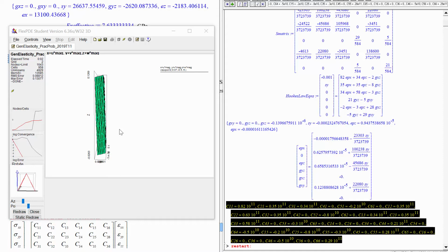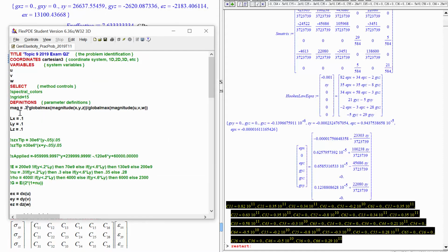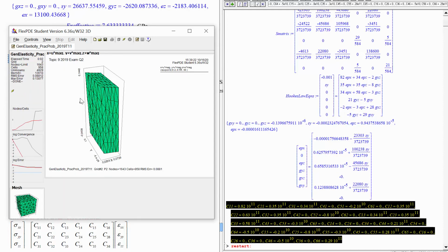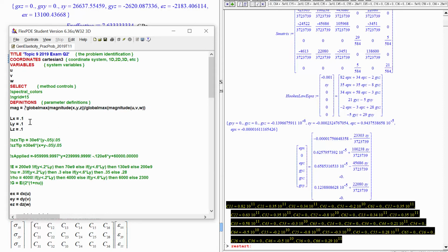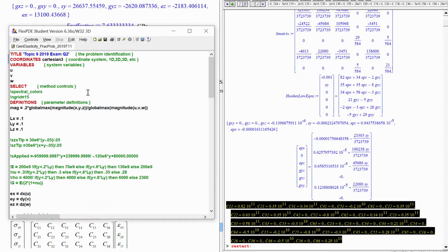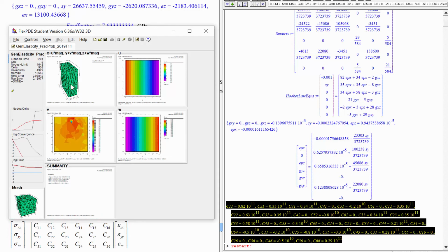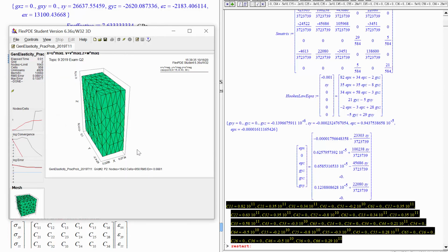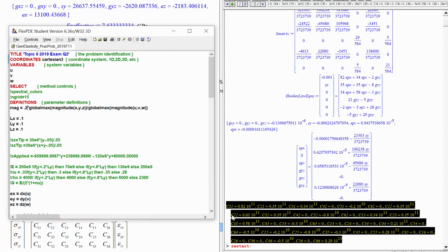We have this relative magnification factor going on right now, where we take the maximum magnitude of position originally, and divide that by the maximum displacement. So this is scaling the maximum displacement to be 1/3 of the maximum position. If we were to multiply it by 50%, we might get the cube to kind of fold into nothingness and extend in the other direction, right? Increasing this more is going to make the cube look like it's getting larger and not moving as much, but that's because it's folded in on itself. So the displacement is really extreme in this case, and the magnification factor we're usually using is perhaps a bit misleading and not the best thing to do if you were to have a 50% magnification factor here.